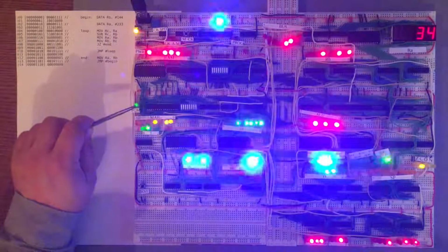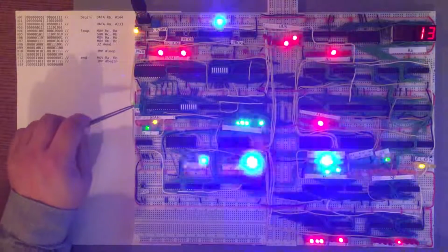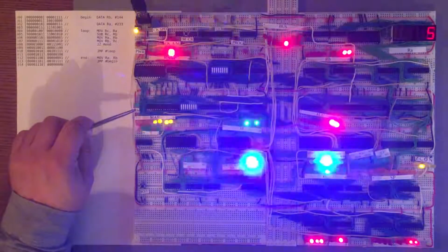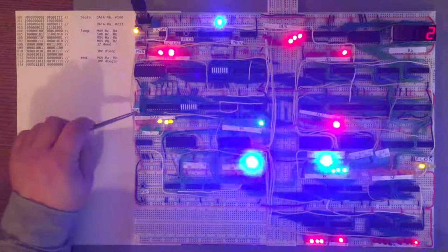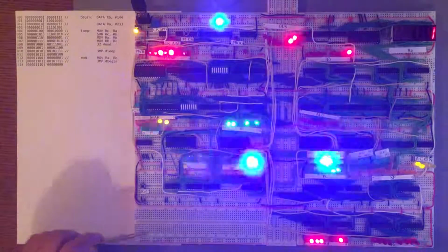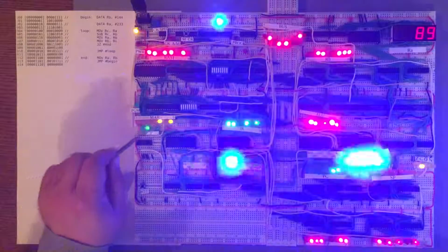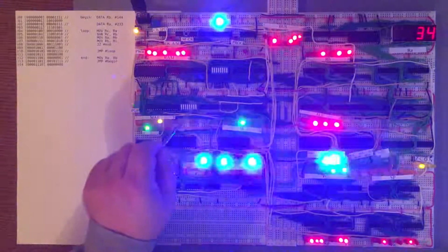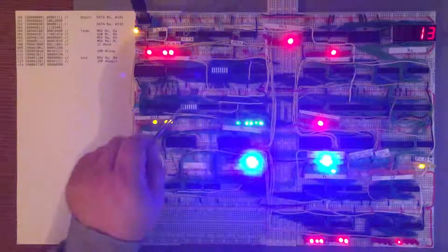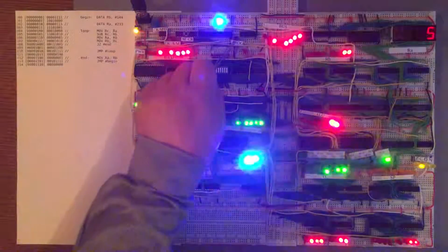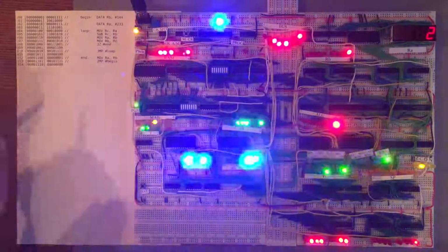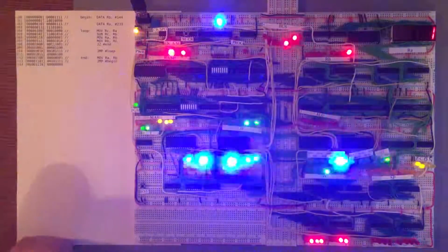And so we're switching between these 2 RAM halves, if you like, using a signal here, which we're calling program memory. And so we'll have a look at how that works in detail. Apart from that, we have a memory address register, which is this one. And we also have dip switches, which are these, which we can use by switching the memory into programming mode. We can actually enter this program into program memory.